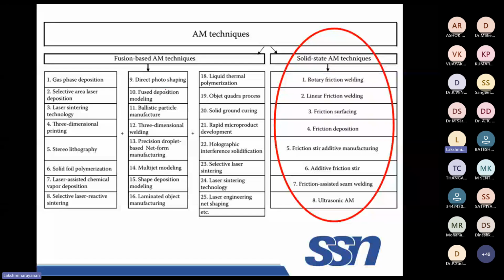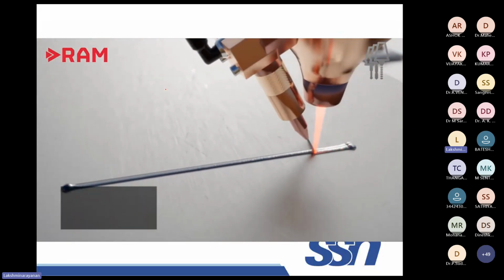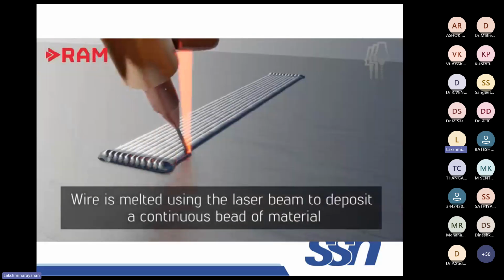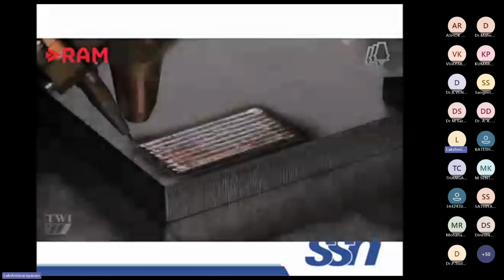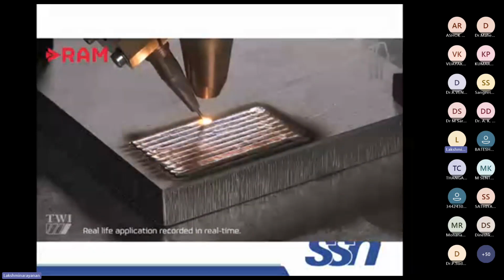So this is the laser based DED, directed energy deposition, where the wire is fed directly to the laser beam source. Once it is melted, you can plan the path using CNC control and directly deposit whatever material.